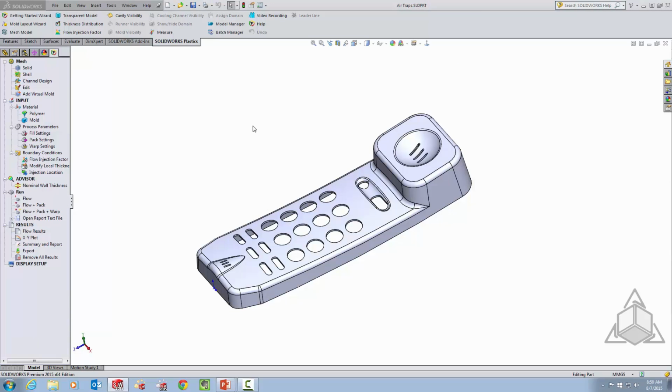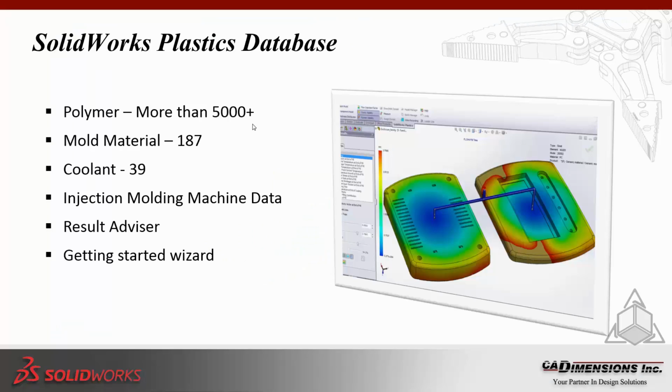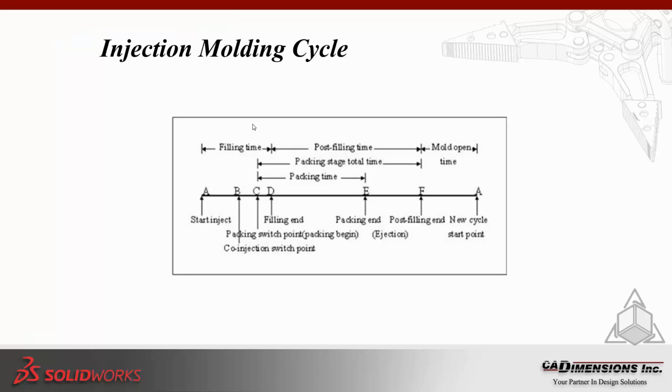Okay, so the next part of this presentation is going to be the filling process. Before we jump into that, I just wanted to give you a quick overview of the injection molding cycle. Now, most of you here probably know this cycle by heart. I wanted to show you this because I wanted to relate it to what the software has to offer. In terms of SolidWorks Plastics, you're able to run a simulation from A to Z. This is all that we cover. So filling the analysis, packing it, so basically the holding phase where it's packing and cooling down.